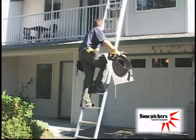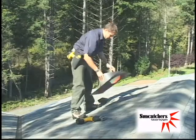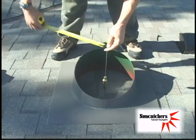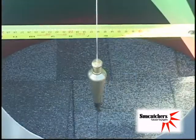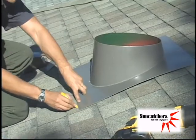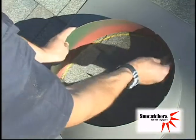First, make sure that your ladder is safely secured and meets all local safety standards. Place the flashing over the screw and center using your plumb bob and tape measure to ensure accuracy. Once the flashing is centered, make marks at the bottom of the flashing for future reference. Trace in the entire inside of the flashing with your crayon.